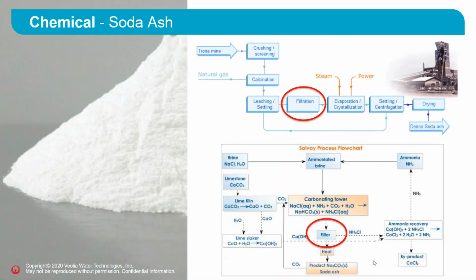We've also installed Precoat filters for the soda ash process. This is a typical schematic for the soda ash process. Here, the limestone and coke is heated in a kiln and then bubbled through an ammonium chloride salt solution, which precipitates the sodium bicarbonate or soda ash. The Precoat filters that are used here usually filter the soda ash particles from the ammonium chloride solution.